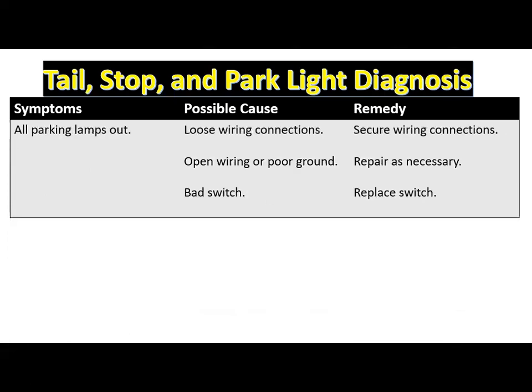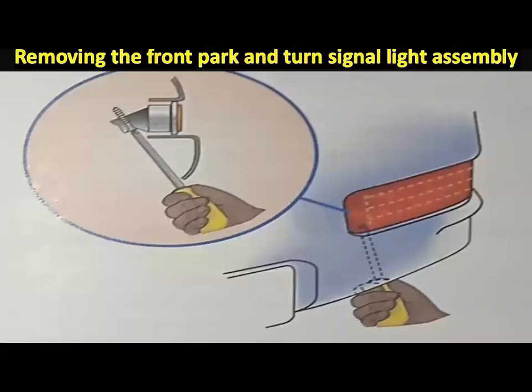Then another symptom is all parking lamps out. Loose wiring connections: secure wiring connections. Open wiring or poor ground: repair as necessary. Bad switch: replace switch. Okay.